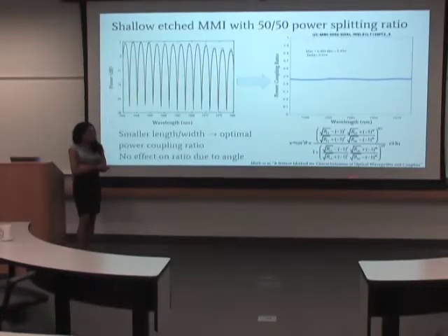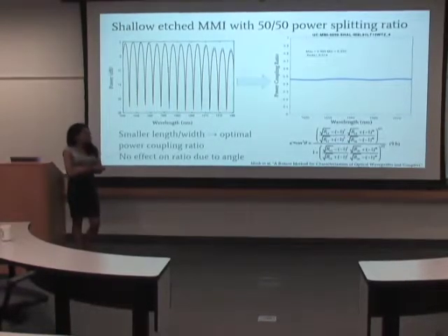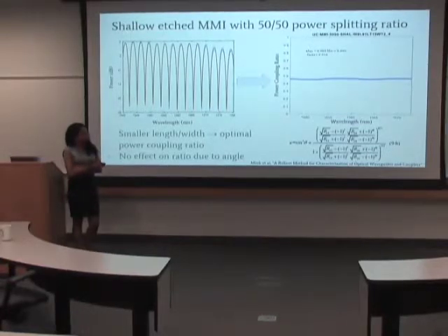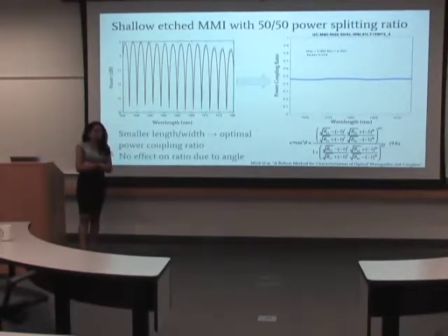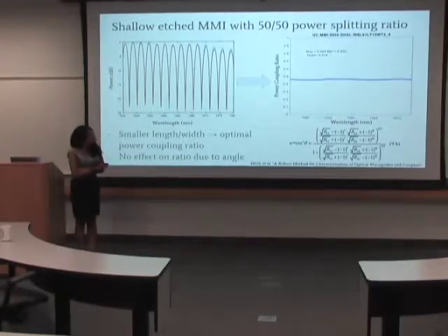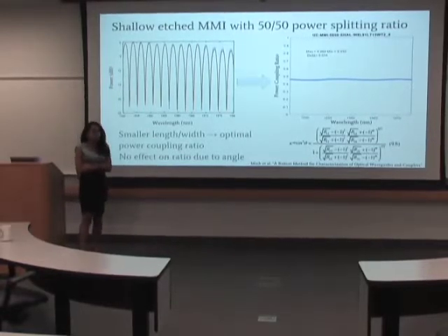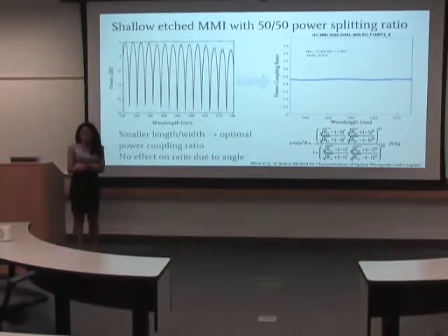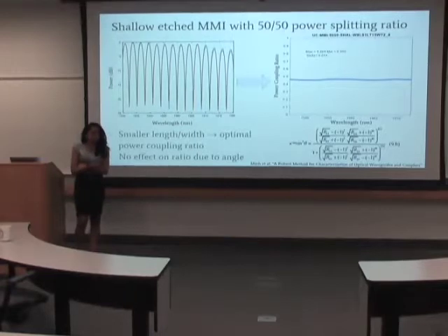So by using this, we created this device that my mentor created. It basically inputs the light through port 1 and travels through the MMI where it's coupled and has 2 outputs, which go into a UMZI, which is an unbalanced Mach-Zehnder interferometer. Because it's unbalanced, there's basically a phase shift, which goes back into another MMI and is read at the outputs of 3 and 4.